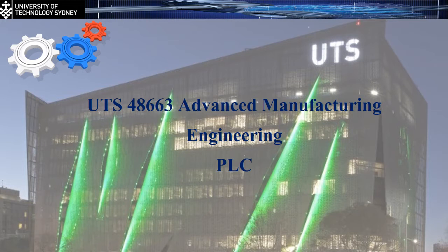So first, before I go through the PLC revision, because I'm going to have a question on the PLC, I would like to tell you something about the calculation we had for assignment number 6. In question number 1, when we talked about the time required for manufacturing using the maximum and the minimum values for the velocity of the cutting tool, we should look for the TU value. So the TU value equation should be used to find the time required to manufacture one piece. There's no TC time we calculate in the first part of the calculation.